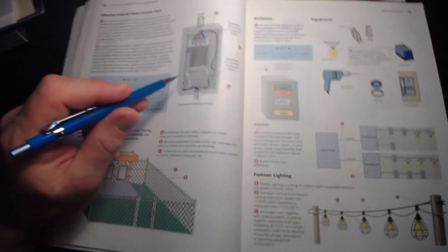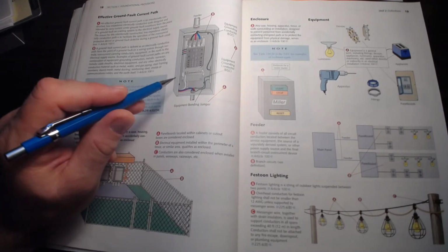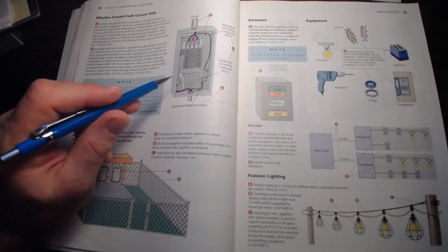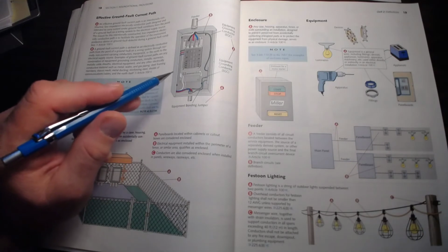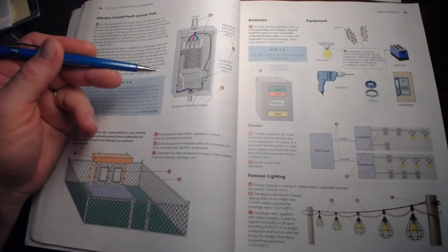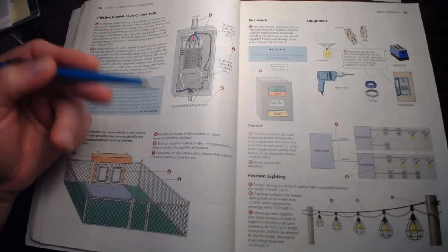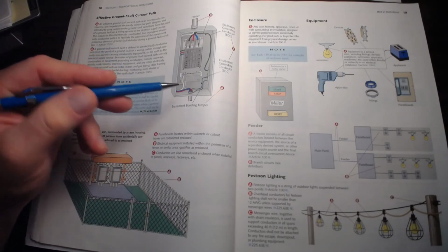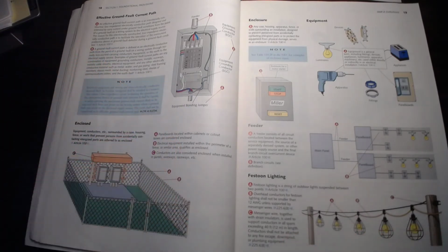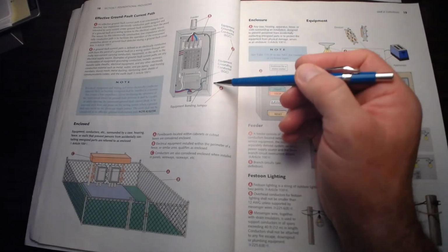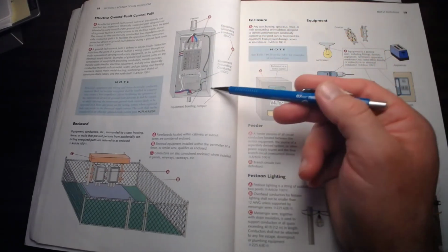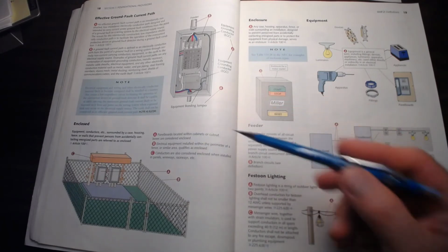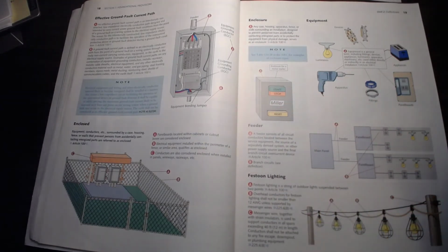I had another issue where the water company had a fault current go on their water pipe system, and it caused damage. And we found out that back at their pump station, they did not have an effective fault current return path, and that's why there was damage caused to their equipment. So the effective fault current return path is going to be ensuring that you have all the bonding and grounding taking place in all of the panels, all of the boxes, and at the equipment level, so that if it were to be contacted by an energized conductor, it would return that current back as fast as possible.